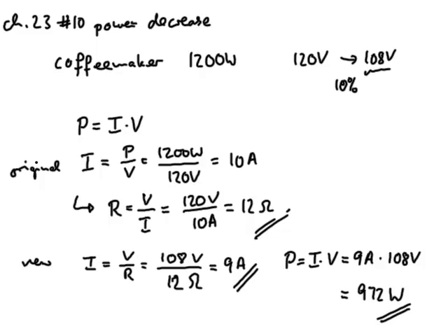But if you went the opposite direction, that could actually be a hazard, because now you would actually draw more power than the appliance allows, and then it may fry itself. So as you go to the higher voltage, pay a little bit of attention, especially if you go to another country where they may have a voltage from the outlet of 240 volts, and where you then should use a transformer.